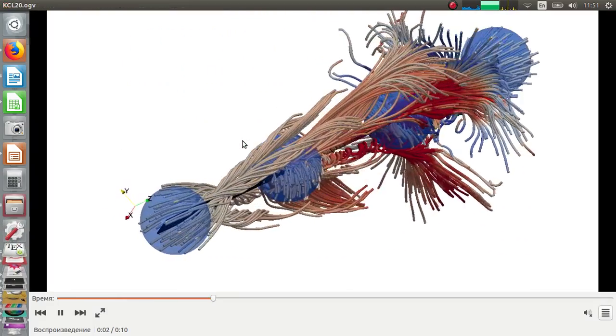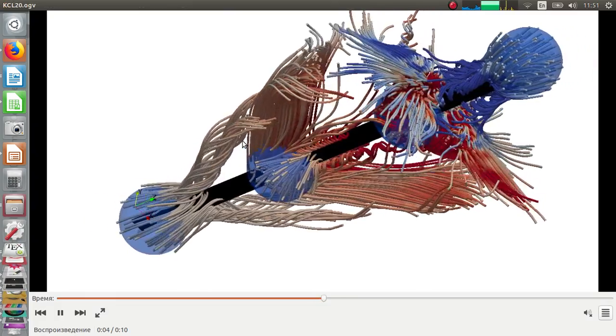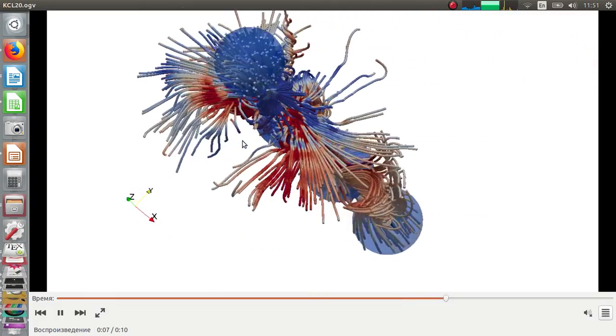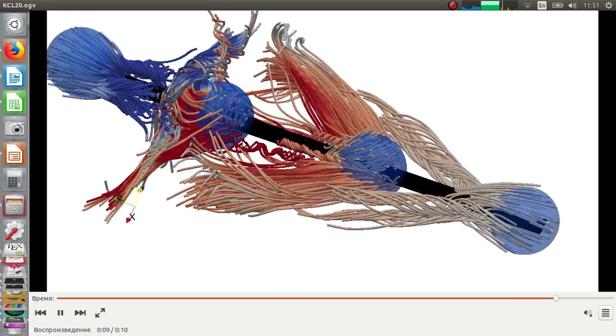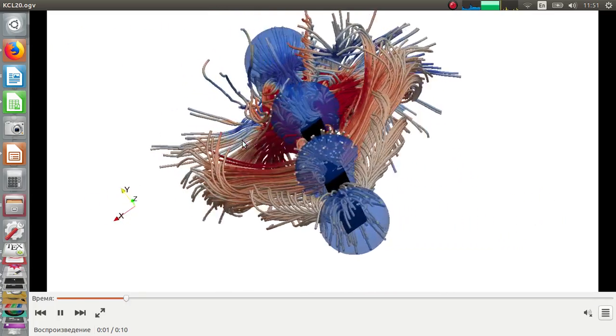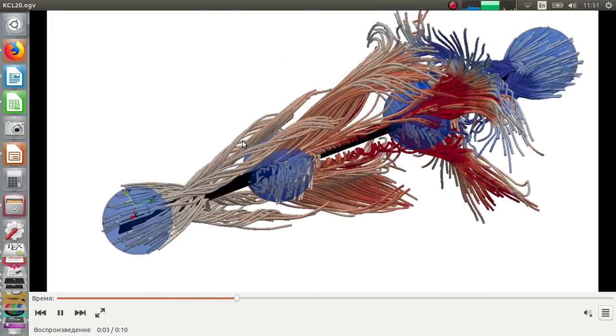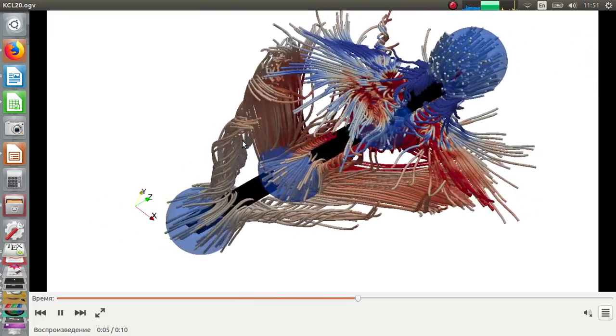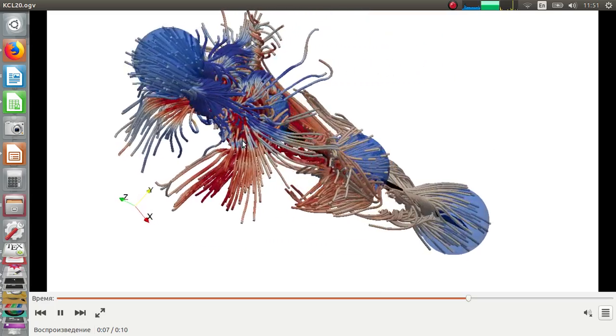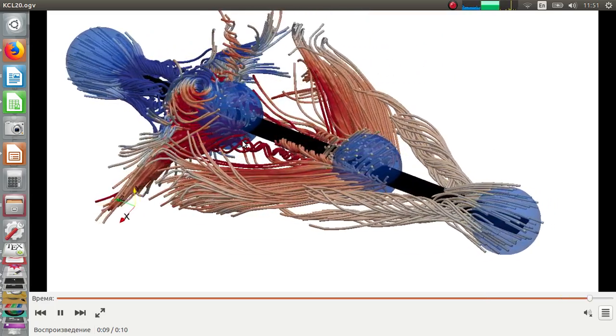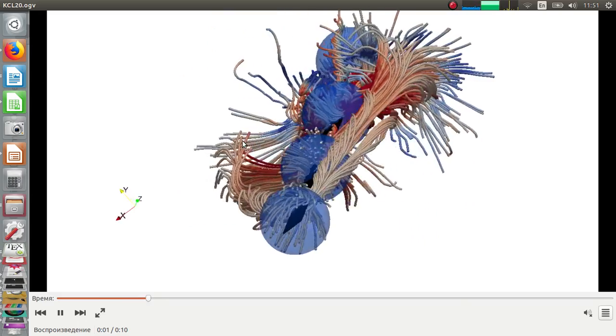For long beams, most of the particles released near the beam, after passing a short distance along the beam, leave its boundary region and enter the outer flow. Such behavior clearly indicates the dominant role of transverse flows. The zones where transverse flows are absolutely dominant we will call quasi-two-dimensional zones. They cover up to three-quarters of the beam.